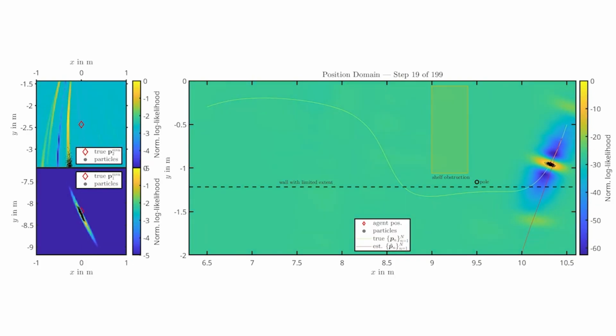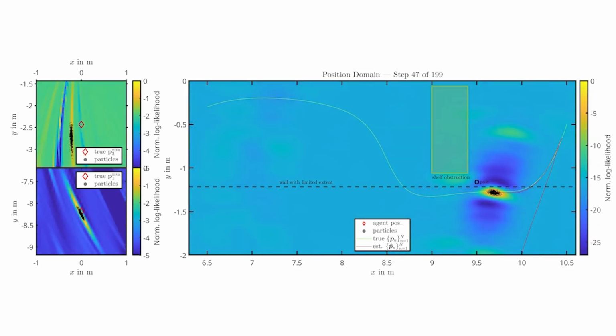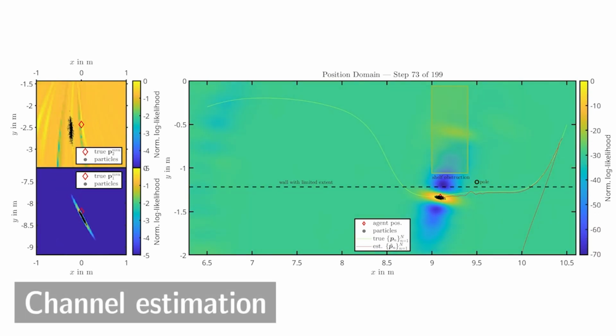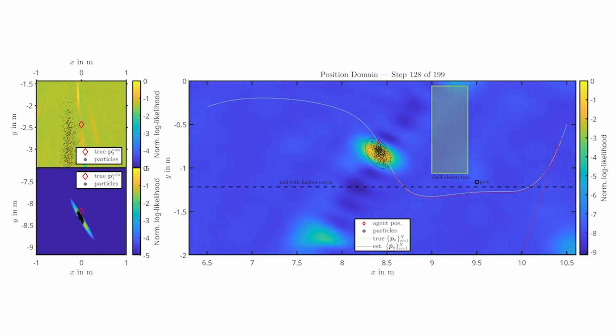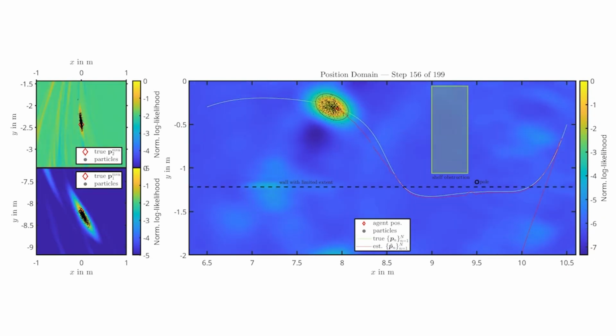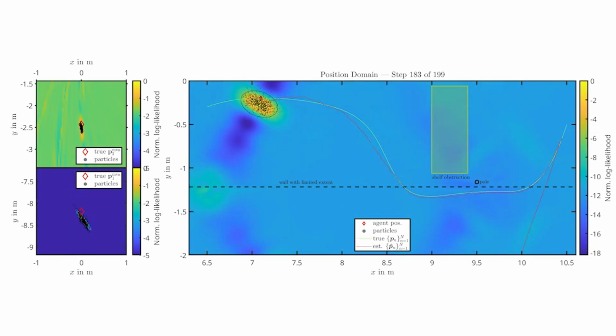We implement Bayesian filtering approximately using a particle filter, where we jointly estimate the three-dimensional agent position and the three-dimensional position and orientation of two walls that have a dominant influence on the multipath channel.